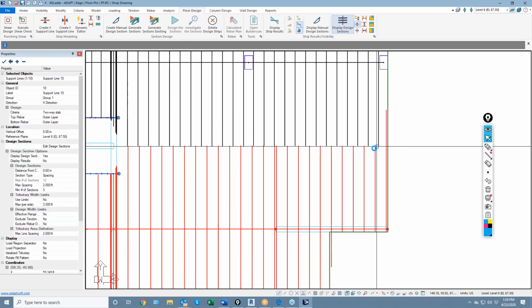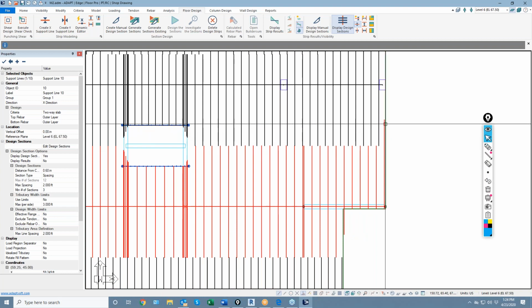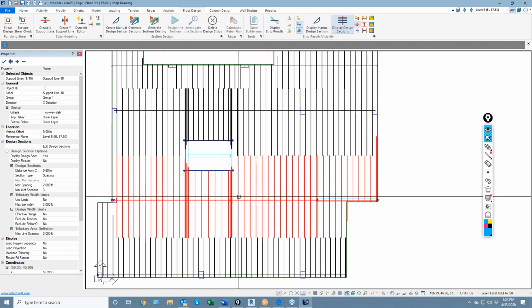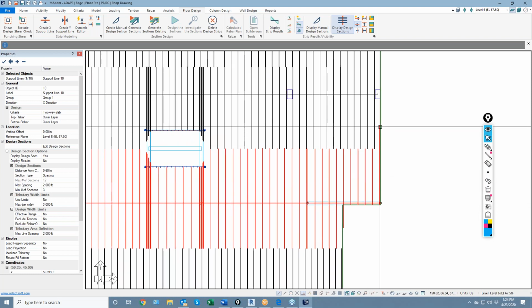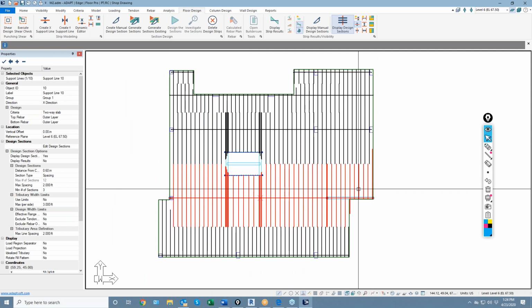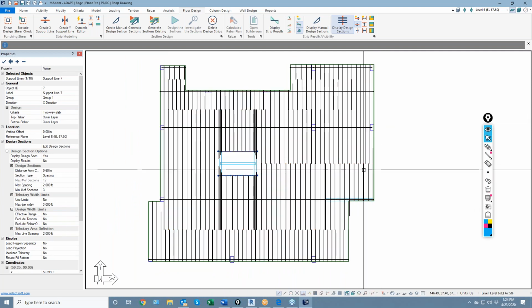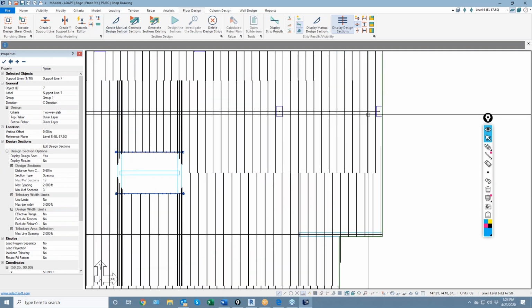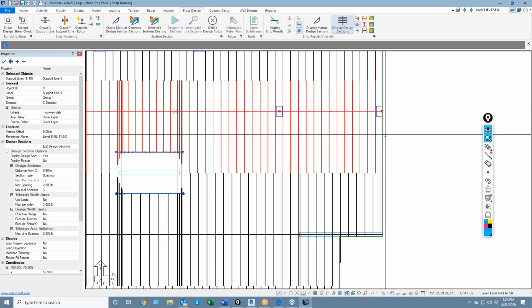This section right there could be detrimental, especially if this is a banded direction and you have one section that's quite a bit longer than the other sections, because the program uses the section geometry to determine the force that it maps. In this case, there's a cutout in the slab, so this section is roughly equal to or less than these larger sections. So it's not a big issue here, but if we wanted to resolve that, we could take this over to the edge.